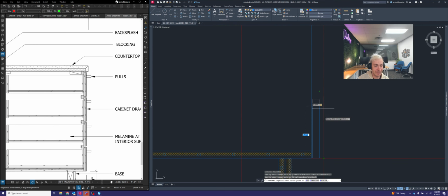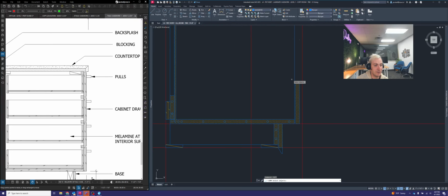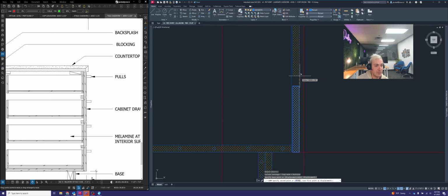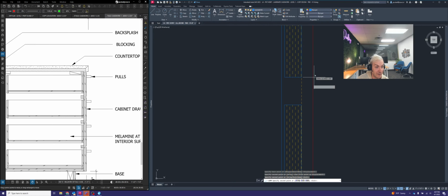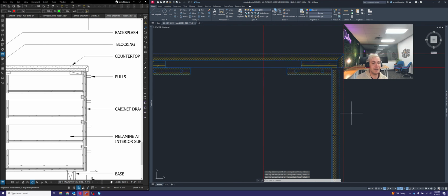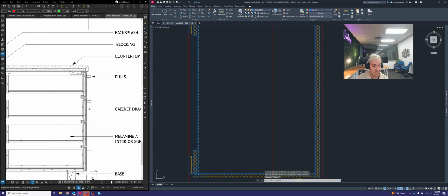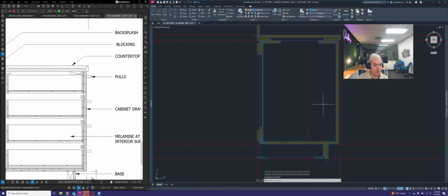But what I'm going to do is go from this point to this point here, throw in some MDF vertical hatch. So I'm going to go back to on-site annotation, hatching, MDF vertical hatch. And I'm going to use the copy command to copy these all the way up. So again, being real careful to make sure I'm using those white dots. They are kind of hard to see, I'm sure, on this video, but they are there. So as you're working on that, that's what you're going to use. Got all 4 of my drawer fronts put in.